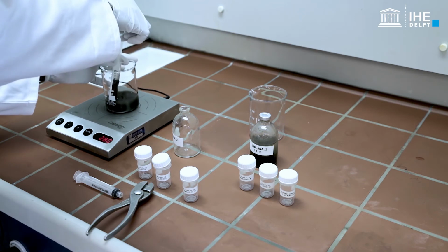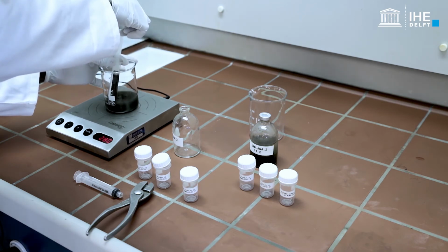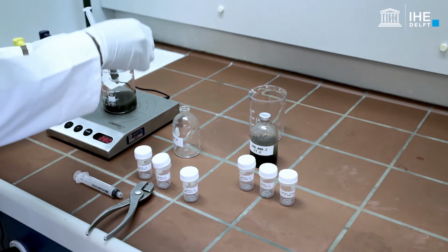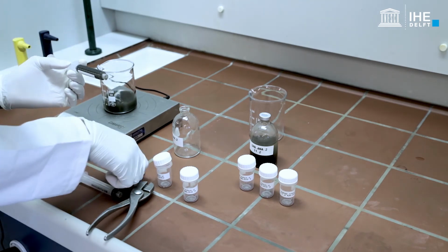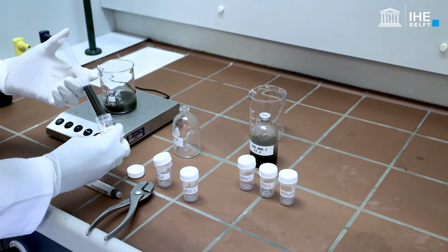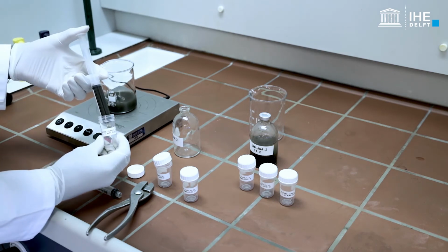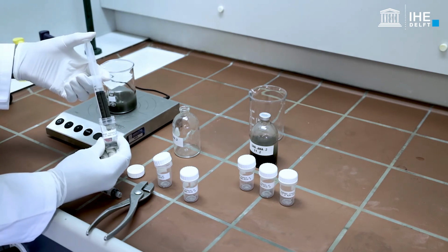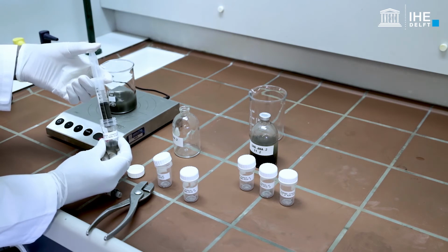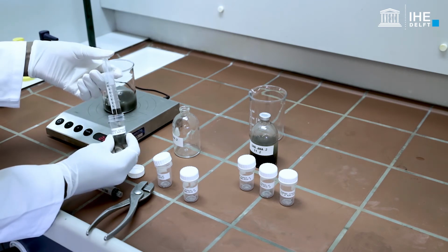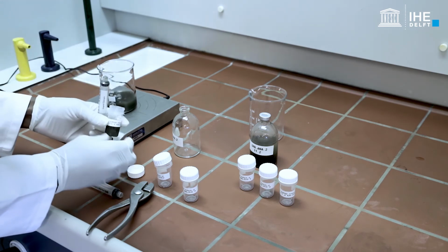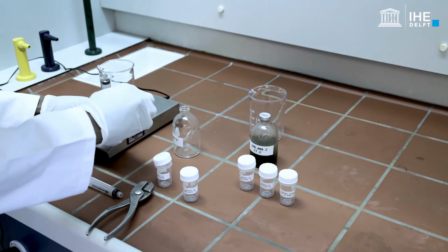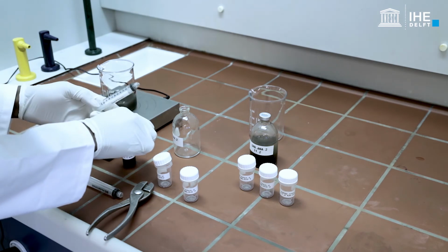Under mixing conditions, collect the liquid samples in triplicate for the determination of the concentrations of mixed liquor suspended solids and mixed liquor volatile suspended solids, and other parameters of interest of the liquid phase. Continue with the collection of the required samples.